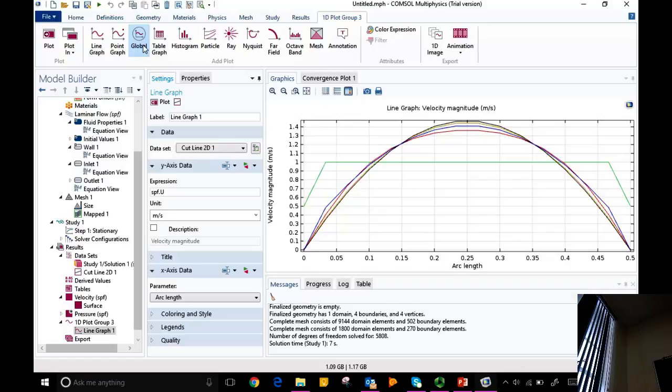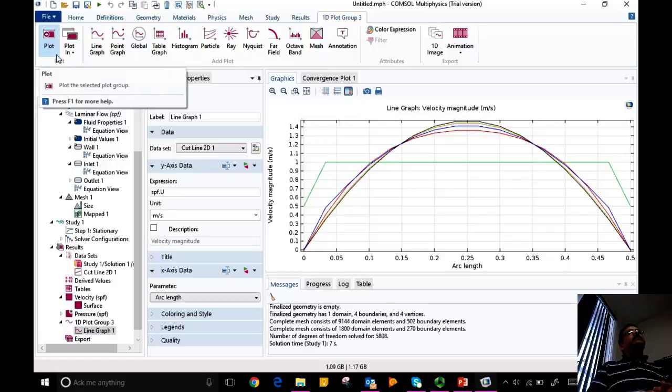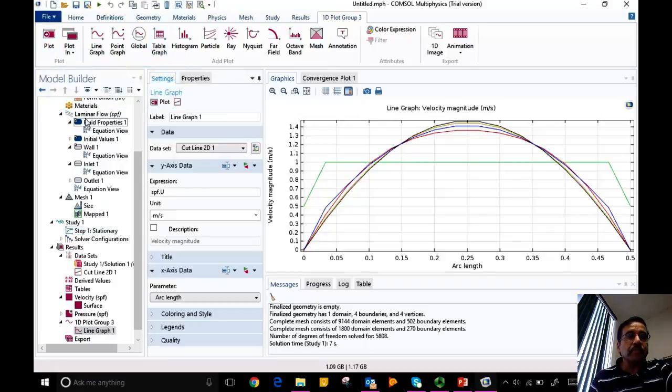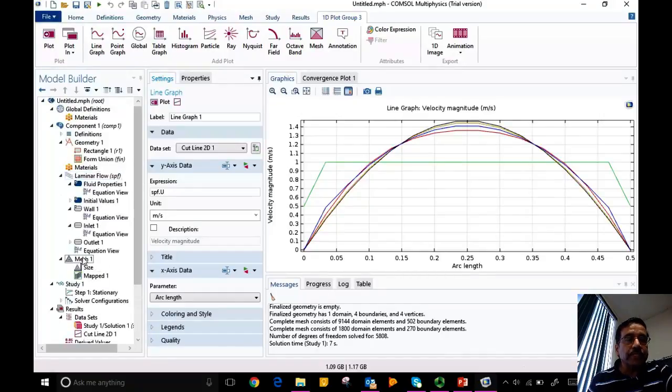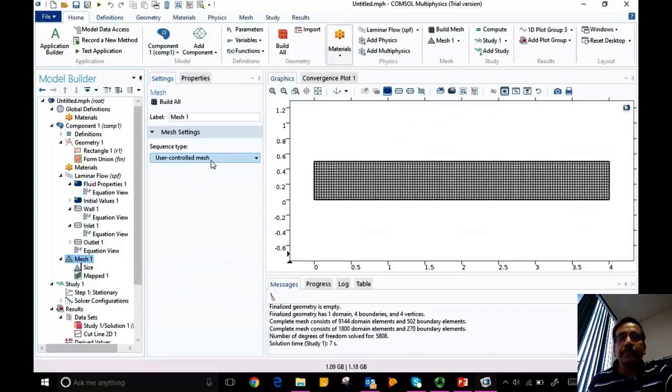So this is the very first line at 0.5. And that creates a big error everywhere. To isolate that error, to localize that error, what do you do? You increase the number of grid points in that domain. Okay. So there are a number of other options in the solution. Let's see whether it shows you here.